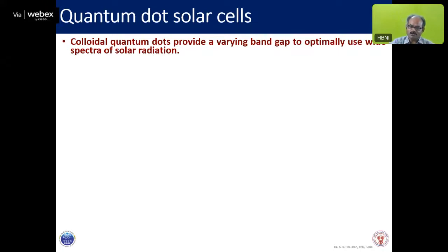So why do we call it quantum? Because the size is very low. Dot means we now have very few atoms, and the energy levels will correspond to those. In the ideal case, even if you have silicon, it will not have the band gap of 1.1 electron volt or a valence band and conduction band, because now it is only 4-5 atoms. If you have 4-5 atoms, at maximum you will get four closely spaced levels at the top and four closely spaced at the bottom.